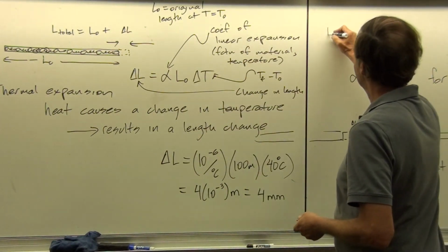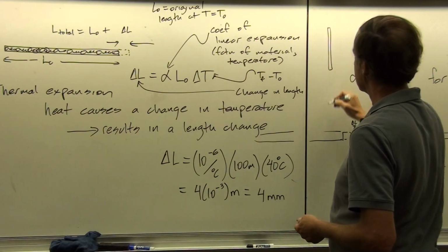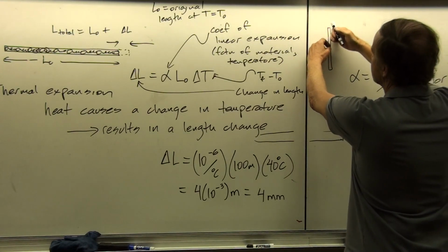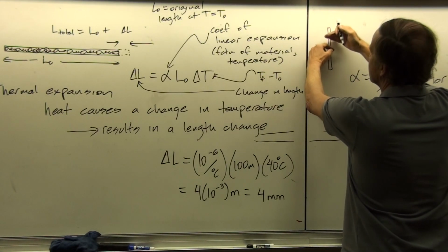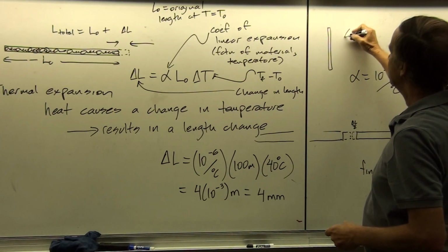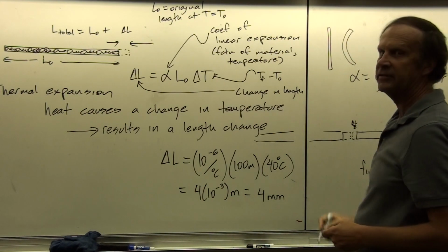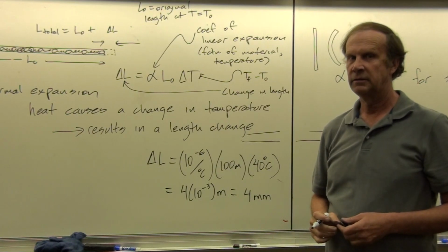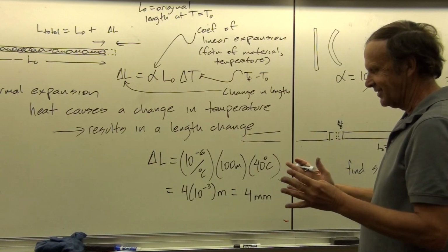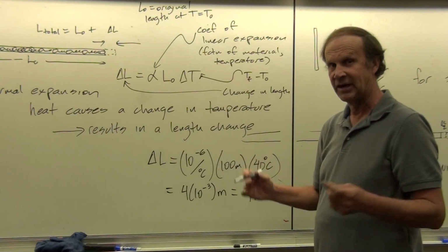But if you just made it a solid stretch of track, hundreds of miles long, and you have this 4 millimeters expansion that's happening every 100 meters or so, that can easily generate enough thermal stress to cause the track to bow. Okay, and to accommodate that stress, and so as the track starts to change its shape, then the train derails.